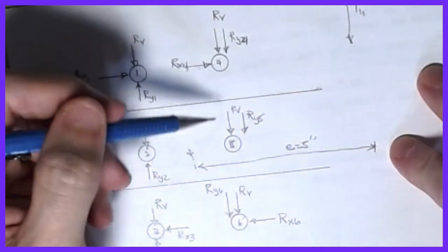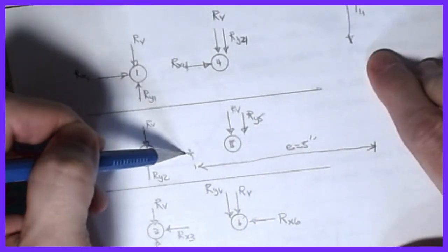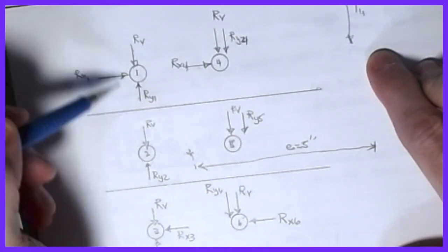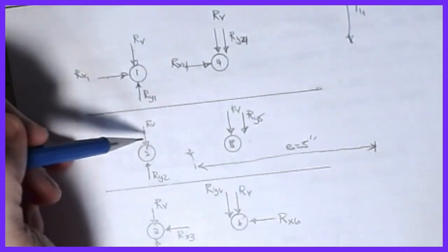So what happens is, relative to eccentric shear, the forces in the bolts on a pattern of bolts become much larger if the bolt is between the centroid and the load, whereas the ones on the backside aren't having to work as much because they're starting to counterbalance the direct shear forces.